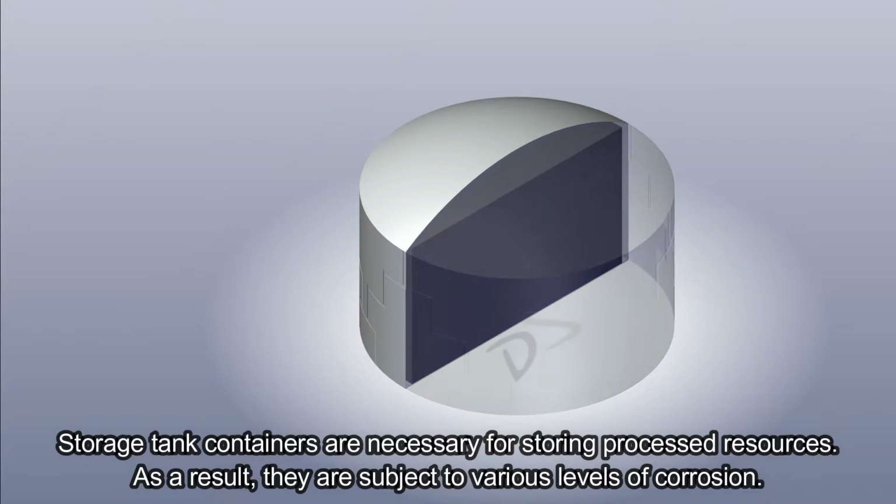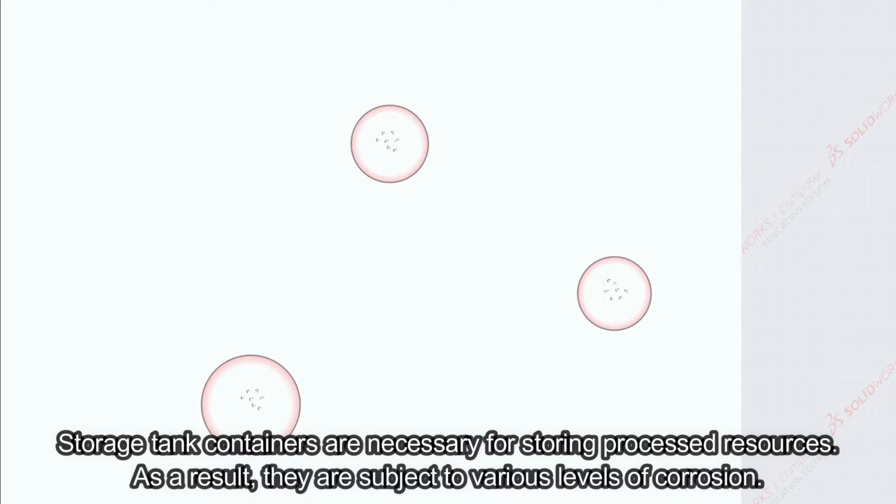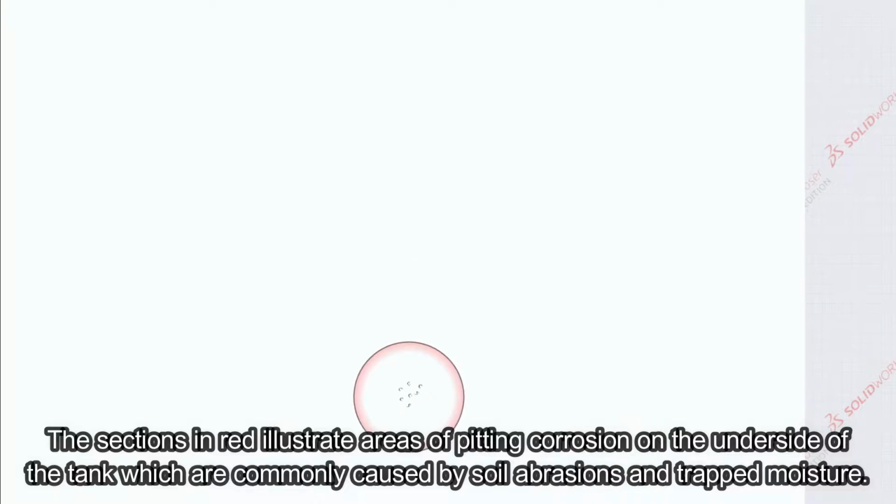Storage tank containers are necessary for storing process resources. As a result, they are subject to various levels of corrosion. The sections in red illustrate areas of pitting corrosion on the underside of the tank, which are commonly caused by soil abrasions and trapped moisture.